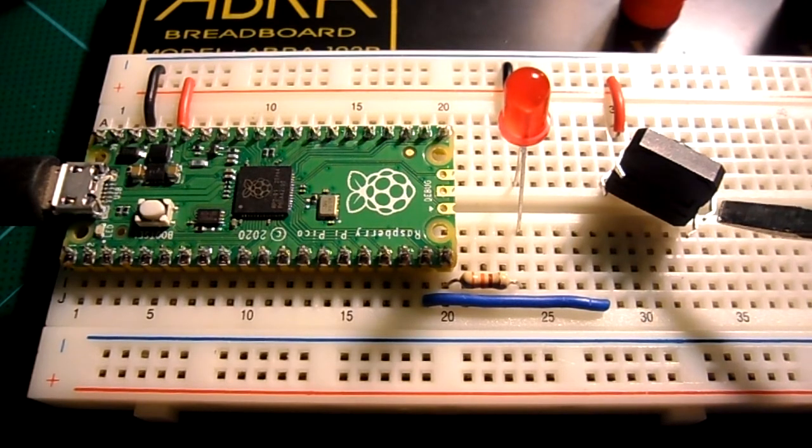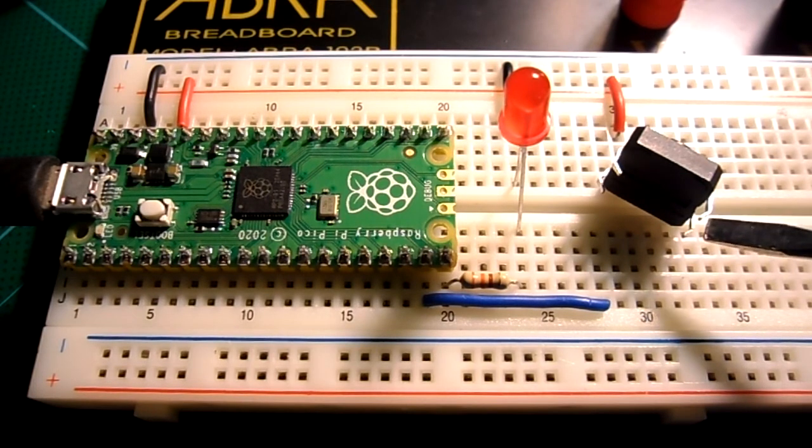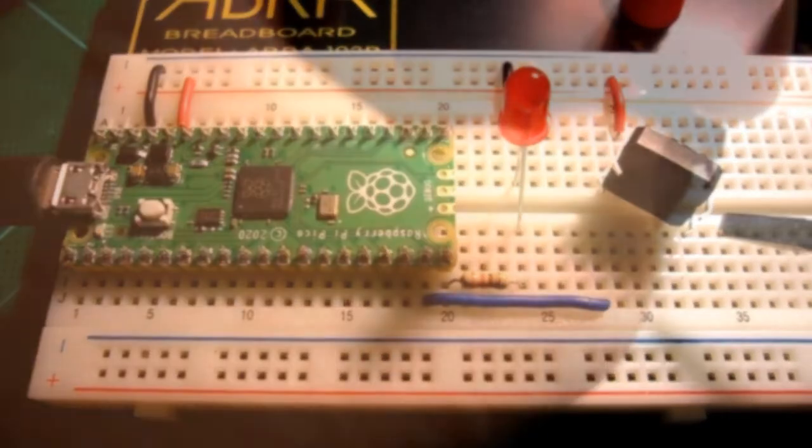So what you're going to need to do is take your needle nose pliers and straighten out these pins, because if you try and press them in bent into the breadboard, they're just going to bend up underneath the switch and won't make contact. So all I'm going to do is come in with my needle nose and just straighten those pins up. So you want them to be able to push in without bending up underneath the switch. So you want to do the same to the other 2 pins on the other side.